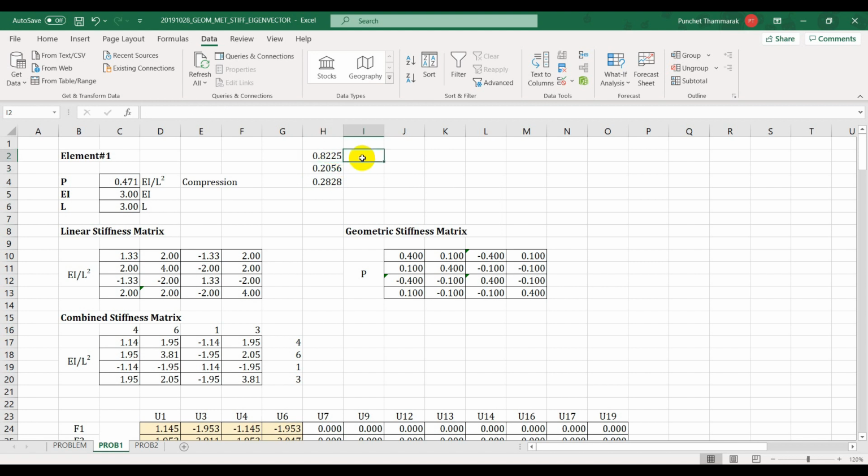This is the buckling load if it is pinned, and this is what we get, 0.47, due to that restraint in the middle. This is on the right hand side column. The load on the right hand side column is 60% of the left hand side column, so it is equal to 0.28.